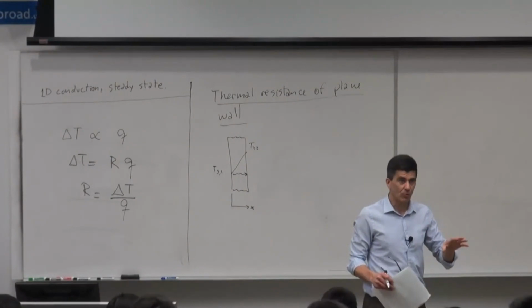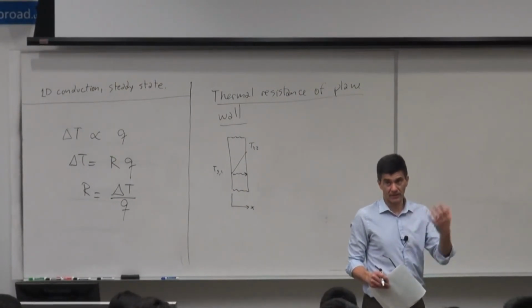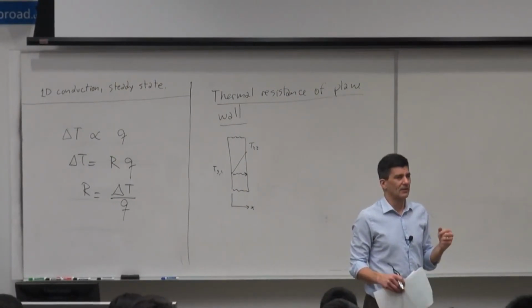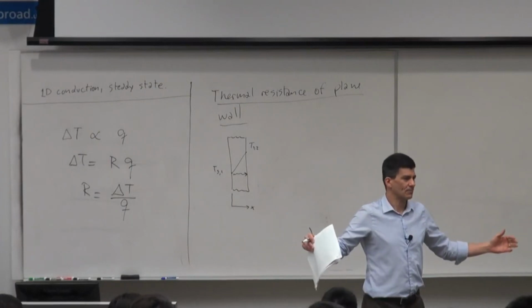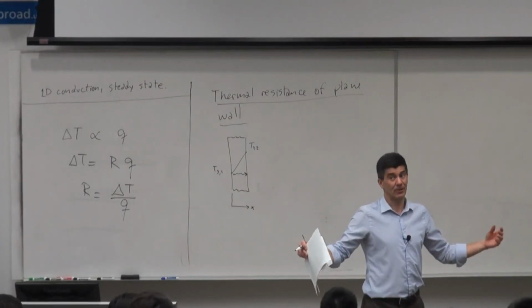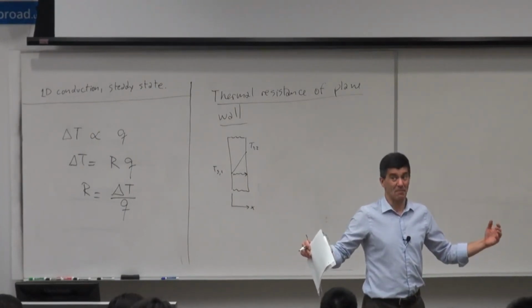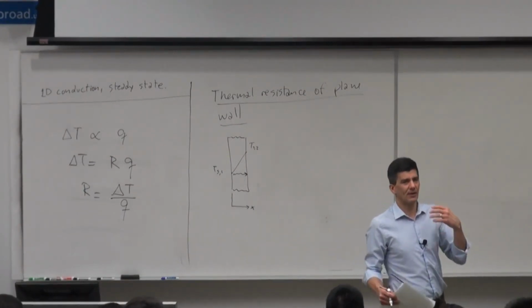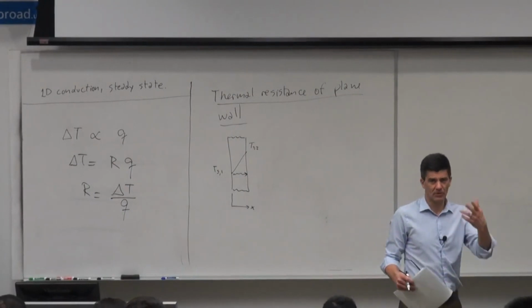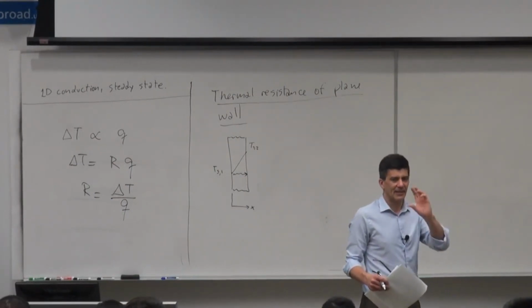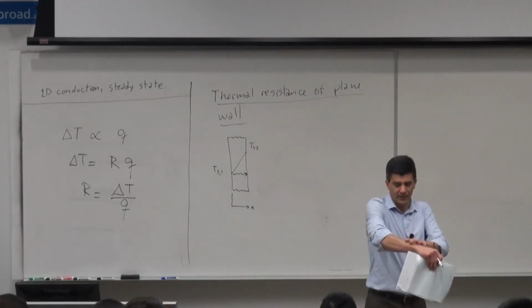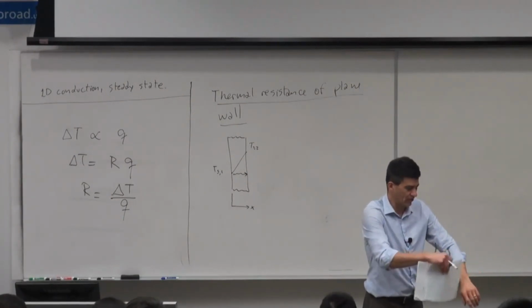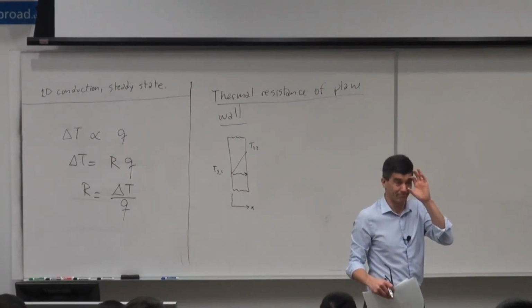When you have those lower temperatures, as you're going to see in the last week of class, the wavelength is much bigger. And this is a funny thing. The transparent glass is black to thermal radiation. So if I bring a thermal camera, and when we do radiation I'll show you some photos, and I take a thermal image of you, not only do you look funny, all in colors according to how you are, but your glasses look dark.